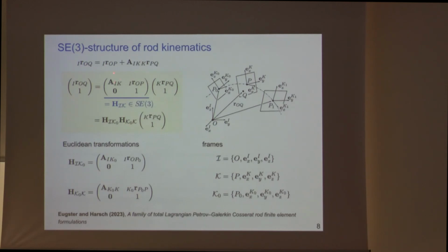And so we have here the center line plus cross-section orientation plus this relative vector between the center line and point Q. And if we add here a 1, so that is actually an affine transformation. If we add here a 1 at the bottom, go to 4 dimensions, then we can rewrite this affine transformation as a linear transformation, which is called a homogeneous transformation.